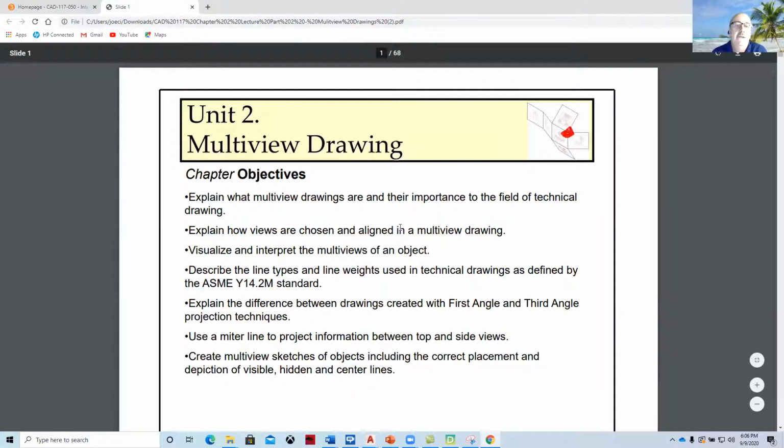You have to remember that CAD has not been around forever. We used to draw on paper, and it's not possible to do these three-dimensional drawings except for maybe an isometric drawing technique versus the modeling. So the way that drawings were represented on paper was with orthographic projection, or front, top, right side views, and even auxiliary views. And so this was multi-view drawing.